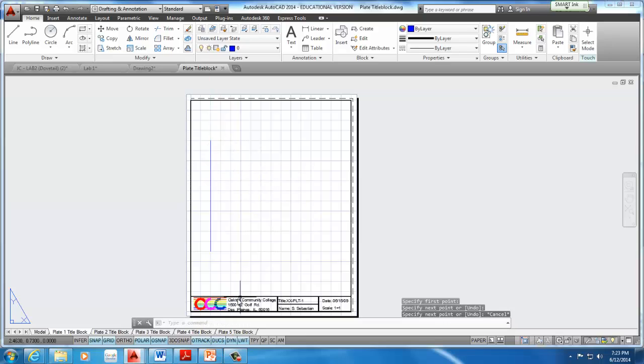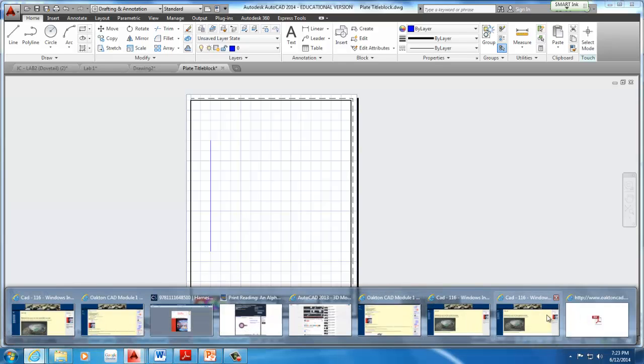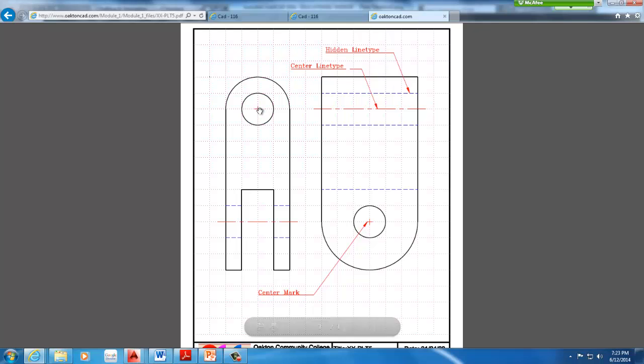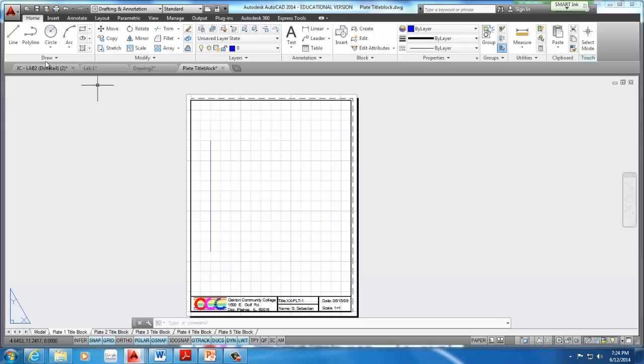And what I just drew was we went up to where that circle begins, because that's an arc. We don't want to create a straight line over that arc. So we're going to go 1 across now, and up 5, and 1 across. From there we're going to use the mirror command, so we'll know exactly our center is right here, and we'll mirror it over. If you don't like mirror, for this drawing you can do just regular lines. It's up to you. So we go to line command, we do 1 box, we go up 5.